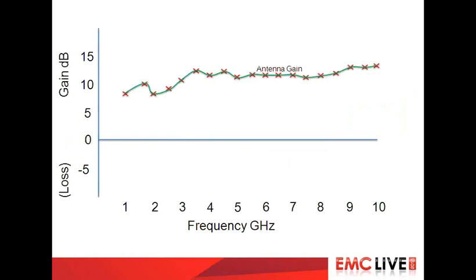And so, I took that from the plot you saw earlier, where I put the yellow lines, intersecting lines to identify, and then I put all the crosses for similar intersections, and I joined them together, and there is your antenna gain, all the way from 1 to 10 gigahertz, the system we're designing. And there is your cable loss. Now, I have loss in brackets on the left-hand side there because technically minus 1 dB of gain is, of course, 1 dB of loss.